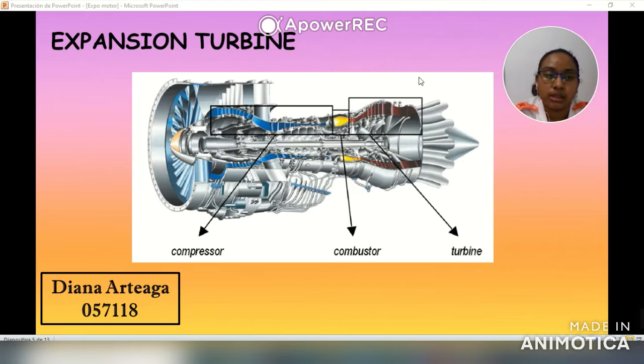The blades must be covered with ceramic material to withstand the high temperatures. In addition, a flow of cooling air from the compressor is passed through them internally, leaving the outside through small holes made along their exterior surface.